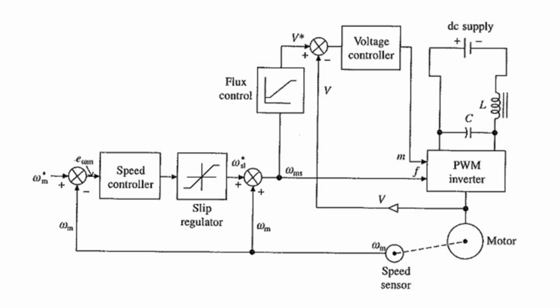Deceleration means regenerative braking, because the braking power flows from the load to the source side. That's why we say regenerative braking. At that time there is maximum permissible current and maximum allowable braking torque until the speed error is reduced to a small value.